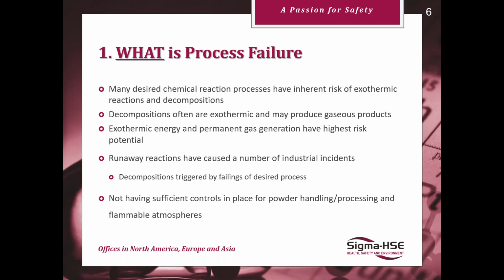So this combination really of exothermic energy, which if not managed properly can lead to temperature increases of the system, alongside permanent gas generation or vapor generation, really have the highest risk potential for any kind of confined system, vessel, or reactor.